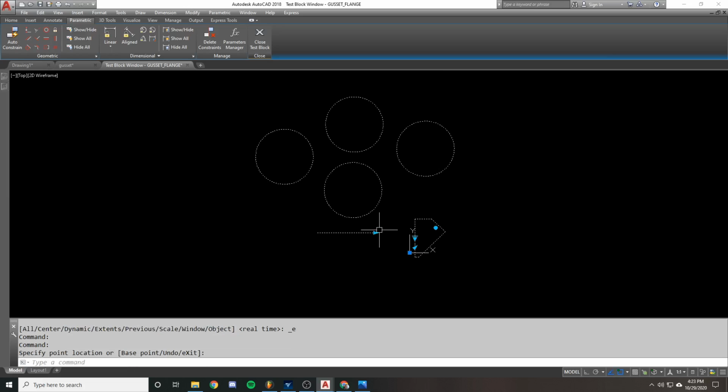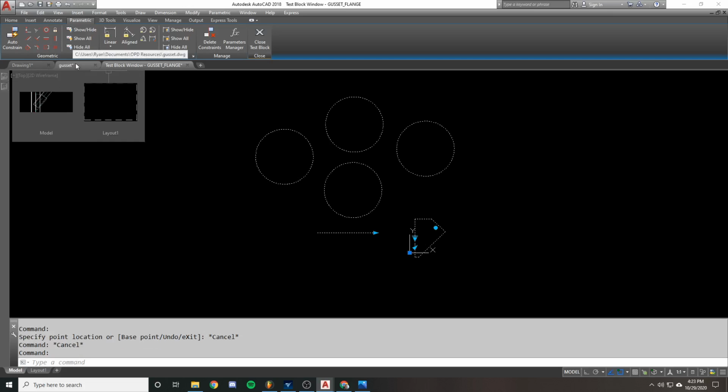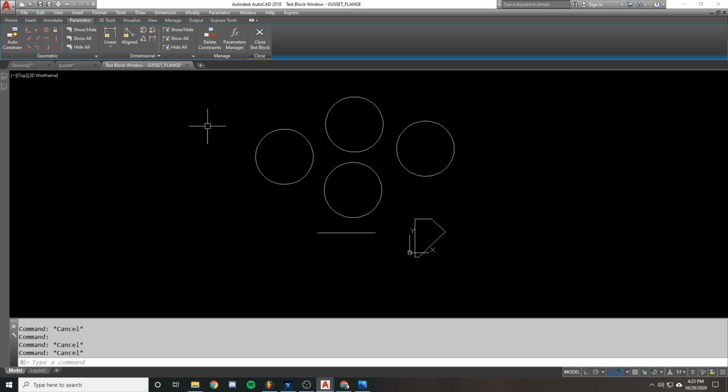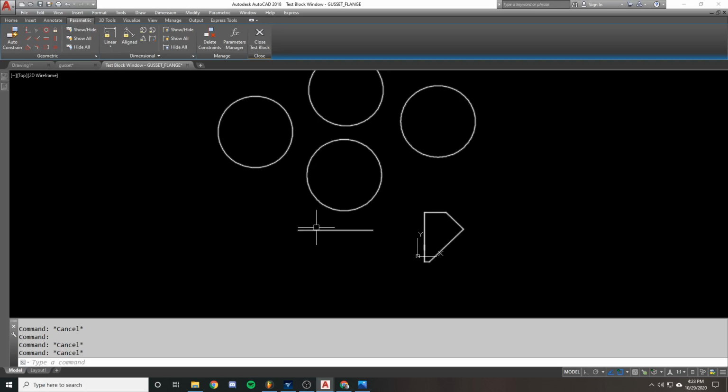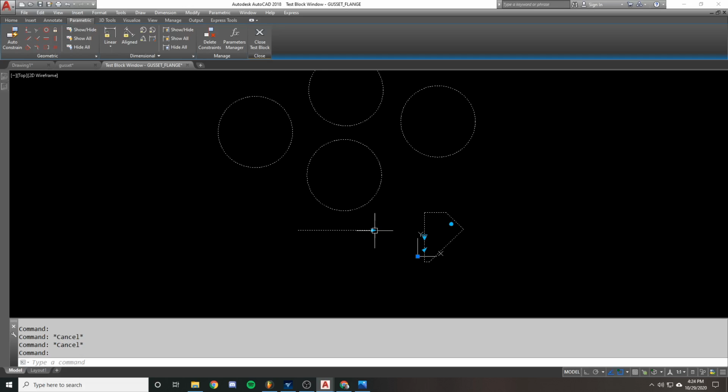I mean, I'm sure you can already think of some awesome things that you can do with that. And what's crazy about this is, I was going to say you can have it affected by a geometric constraint, but you can't. It would be kind of neat if you could have this thing automatically change based on a geometric constraint, but you can't because it's a dimensional constraint. So it's going to be whatever the dimension needs to be. But still, the fact that you can tie these things together just makes it really, really powerful.